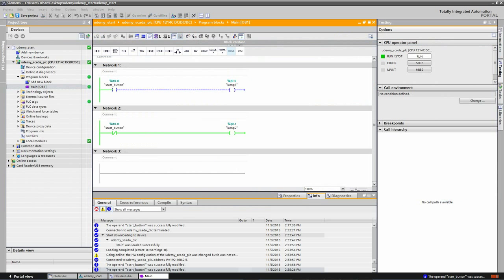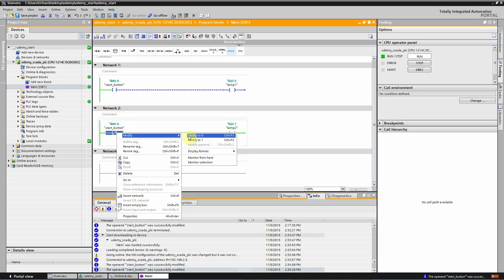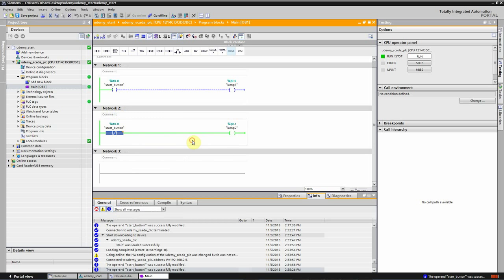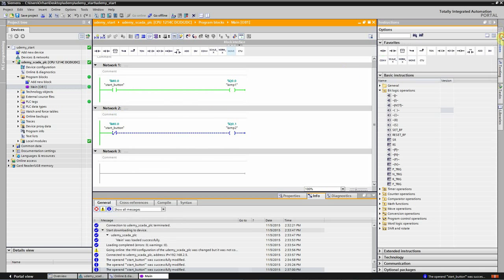After, we will put our system in some button, and we will show you how digital input works. So I will make my memory 0.0 now true, and my lamp 1 is working now. Okay, we can look at basic instructions inside some commands.